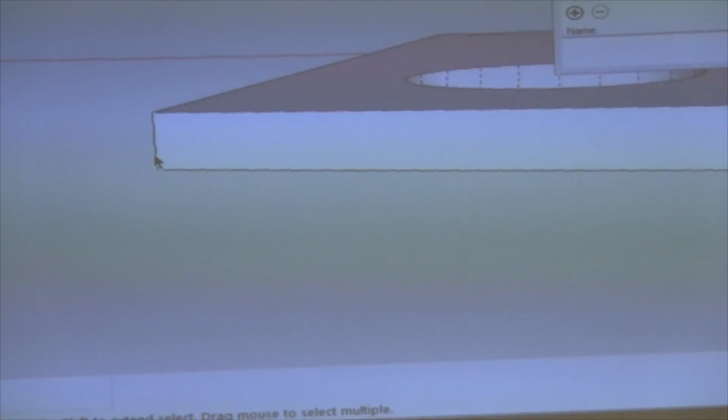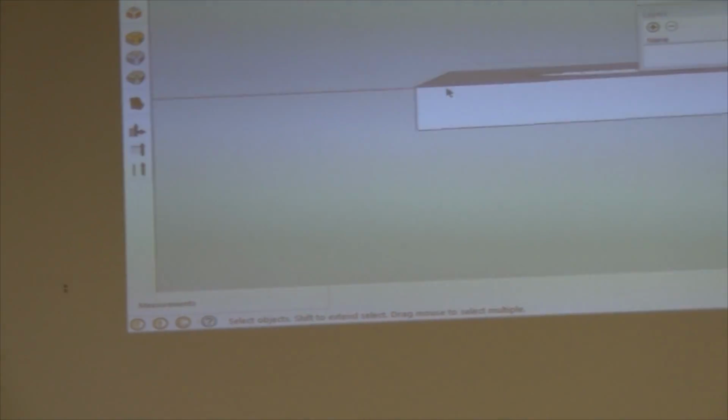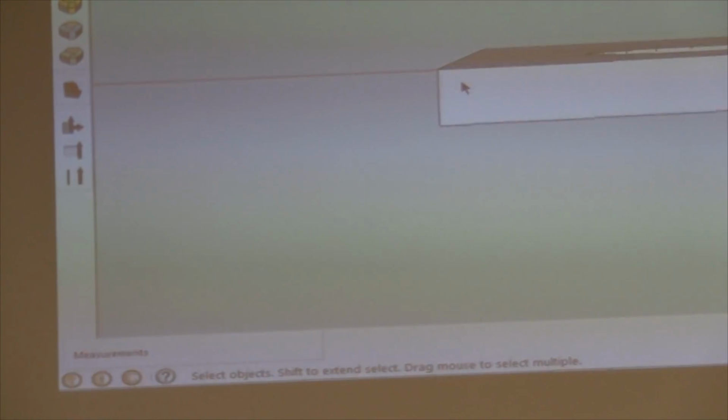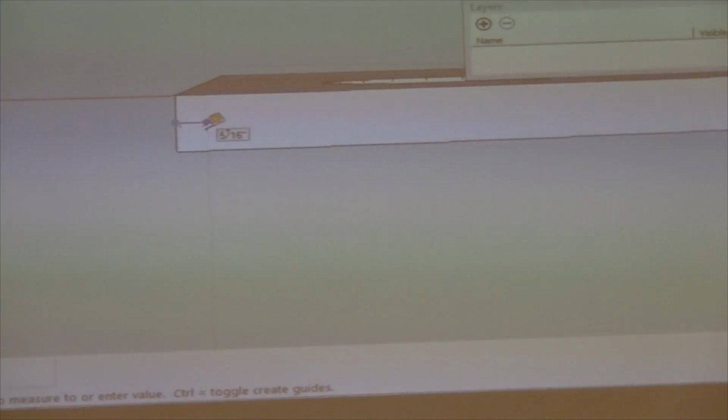So here's how we're going to do that. The back surface is going to remain flush. What I want to do is create a, what is my radius that I want to do? 3/8 inch bullnose. So it'll be just a real nice smooth bullnose off of this 3/4 inch piece. So I'm going to take my measuring tool and come over here, 3/8 of an inch.